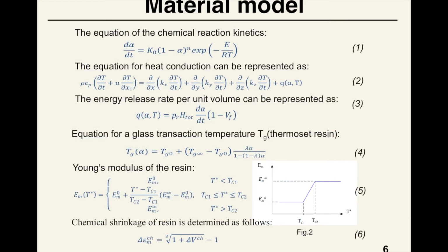One of the key processes during manufacturing of composite part, and at the same time a bottleneck, is the polymerization of resin that takes place inside the die. At least three kinds of constitutive laws, elastic and pseudoelastic, cure-hardened instantaneous linear elastic, and viscoelastic law are currently used to predict curing process-induced residual stress for thermoset polymer composites.